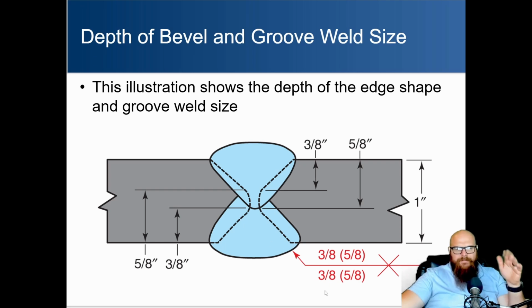The welding symbol would be indicated as shown here, where we have the arrow side pointing on the bottom. Both of these things are going to repeat, so you're going to have parentheses that are going to tell you the depth. The bevel is going to be outside of there, and then you've got the double bevel groove on there. This one doesn't indicate what angle they need to be at. They don't always need to do that, and if it doesn't indicate it, then it's just up to the person actually completing it what they're going to bevel that stuff to.